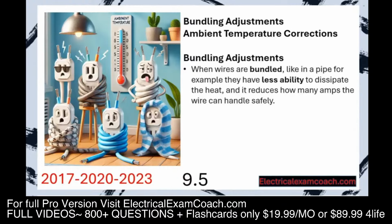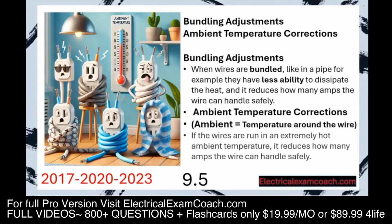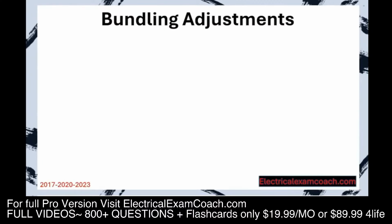When wires are bundled, like in a pipe for example, they have less ability to dissipate the heat, and it reduces how many amps the wire can handle safely. Ambient temperature corrections are like this. If wires are run in an extremely hot ambient temperature, it reduces how many amps the wire can handle safely. We're going to learn about these one at a time. Let's get to it. Let's dive into bundling adjustments.